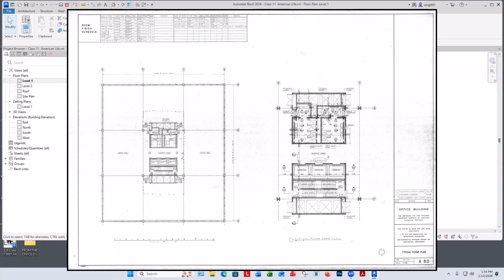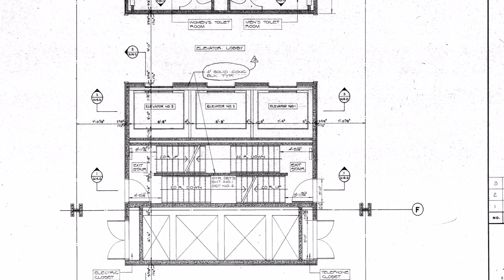So you can see sort of overall what we're dealing with is 2 cores that are centered between 2 pairs of grid lines. They're sort of set in the middle of them, going this way. We're going to an enlarged plan of the core. So you have 9 feet even from one wall to the next, and 7 feet 7/8 inches from the grid line to the wall.